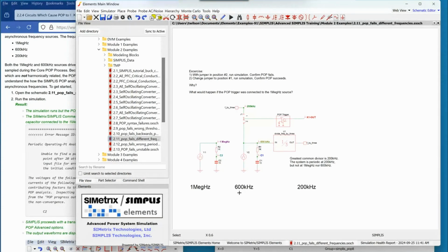So you have to design your battery model so that during AC, a POP AC, you basically switch a voltage source across the cap and switch the cap out of the circuit, so you operate like a constant voltage and it's not changing during POP. And then during transient analysis, if you want to look at charging, you switch back. So at T0 of transient analysis, you switch the capacitor back in.